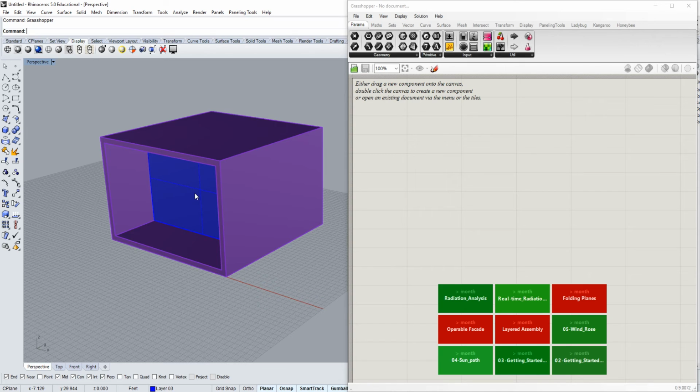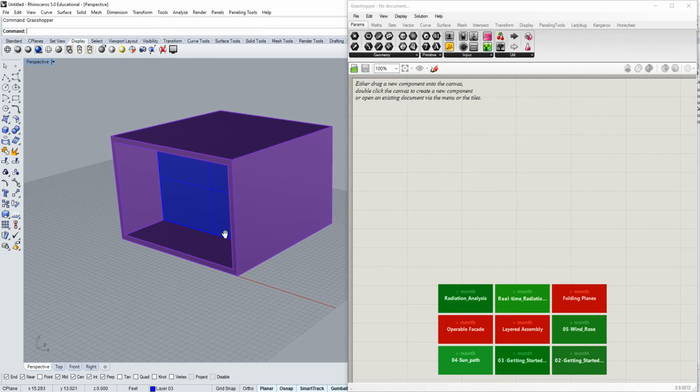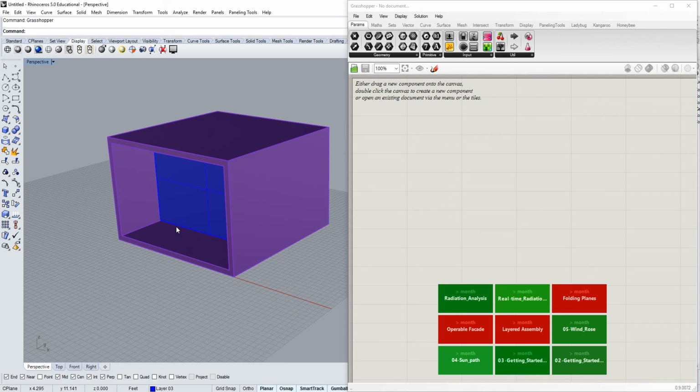So the walkthrough will take us through setting up a guardrail with a reparametrized glass panel in the center, and then we will pipe the actual structure of the rail itself. So to get us started, what we're going to do is actually start to reference in the geometry itself. Since this is going to be a guardrail that sits at the lower 4 to 5 feet of the opening, well, actually, it's not 4 to 5 feet, it's 42 inches. But it'll be at the lower 42 inches of the opening.